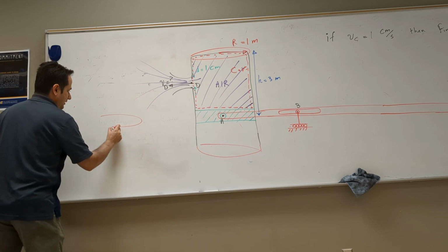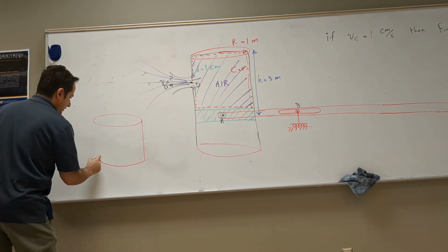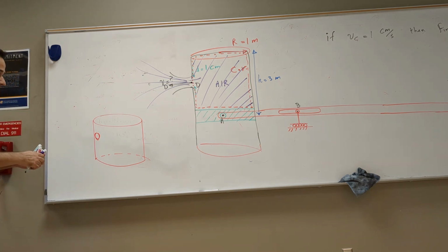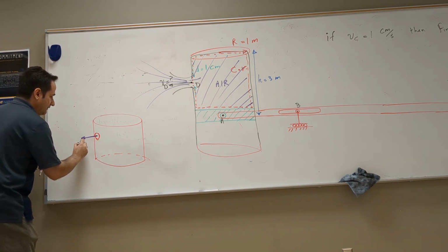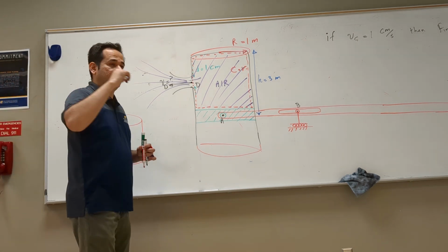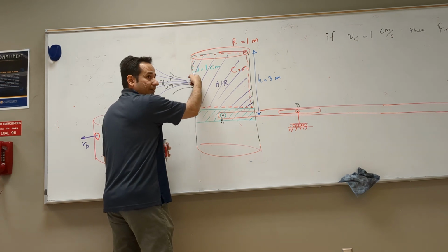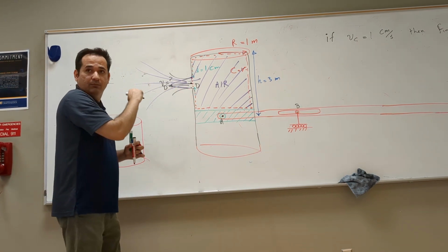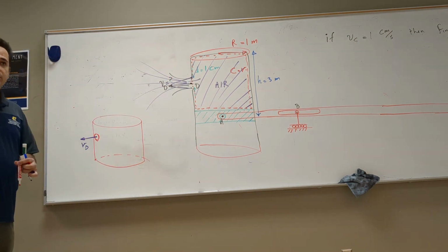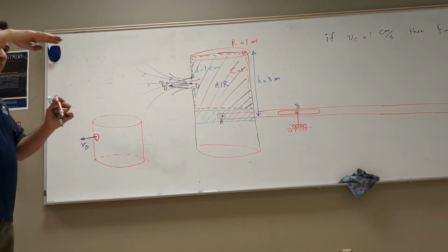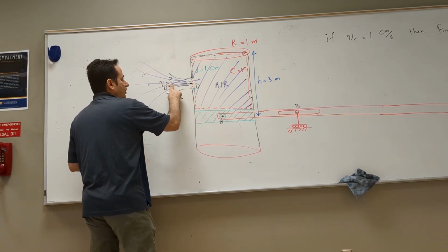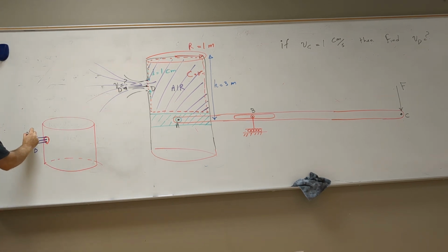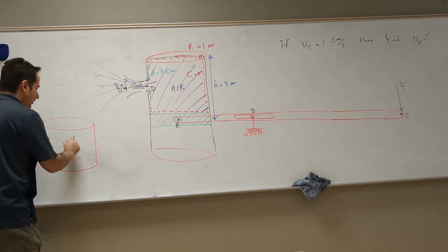Now, for this system, if I can isolate it, let me isolate it here. So you're going to have a cylinder like this, and the bottom one is like that. But also here, you get a cut. And you know that the fluid is leaving from here, and this is V_D. Now you know that in real life, the velocity versus this y changes, right? Here the velocity is 0, then the velocity is maximum in the core, and then goes back to 0. Well, let's say the diameter of this hole is so tiny that the velocities are almost the same. I mean, that parabolic distribution is so sharp that the velocity is just constant everywhere on this tiny surface. And the density of the fluid is also constant.